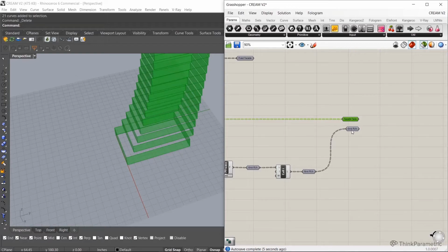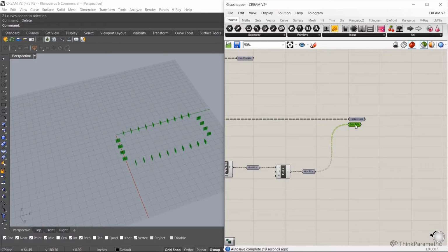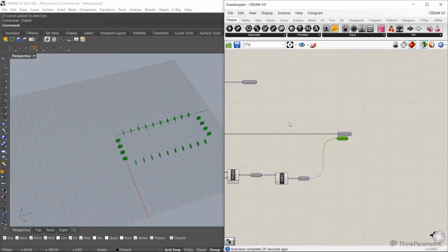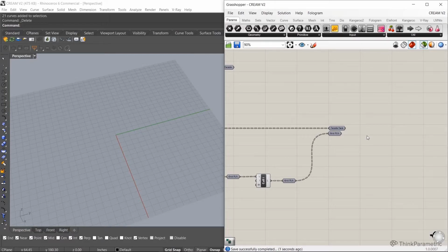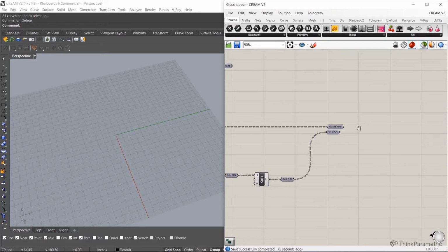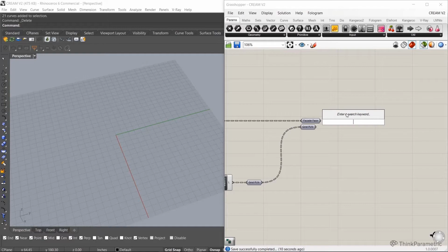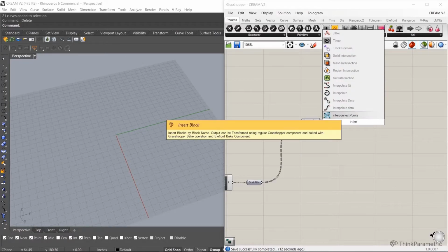So you also see the way that I try to avoid, like every time you're coming out of a component, you have a description thing, and every time something comes in, you have a description component. And where I kind of move vertically, I try and do it in what's kind of known as a chimney. That way you start to create a bit more readable scripts rather than all these kind of like spaghetti scripts that you often see. It really helps when other team members come into this script. If I'm away sick tomorrow and someone needs to work on the script, it helps to kind of guide them as to what's going on.